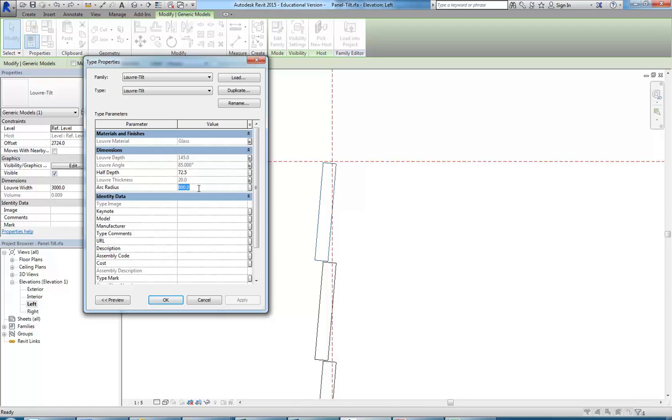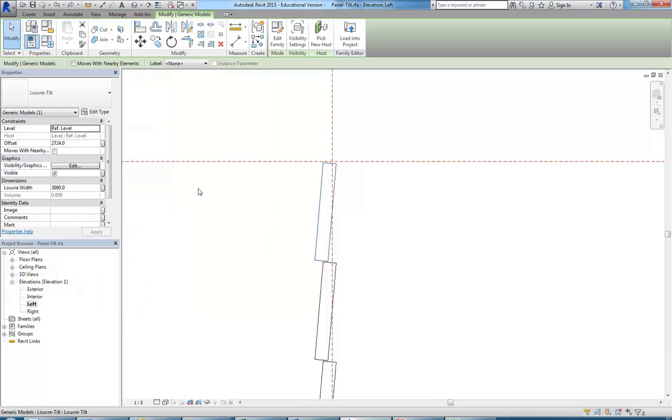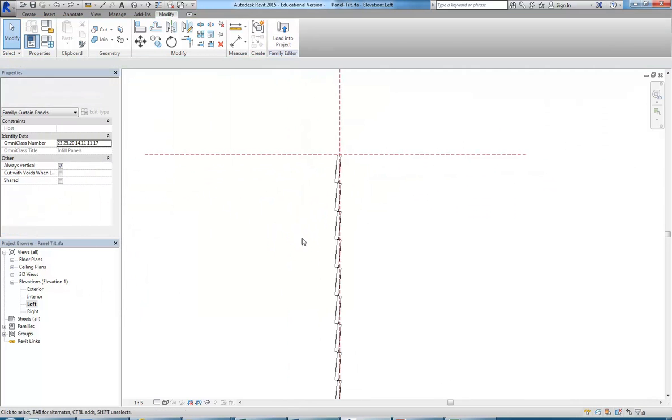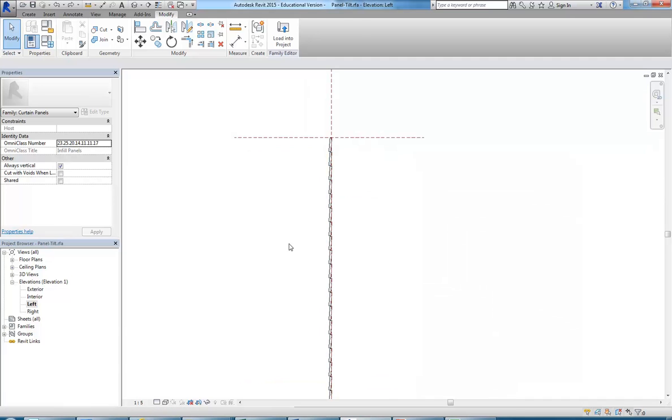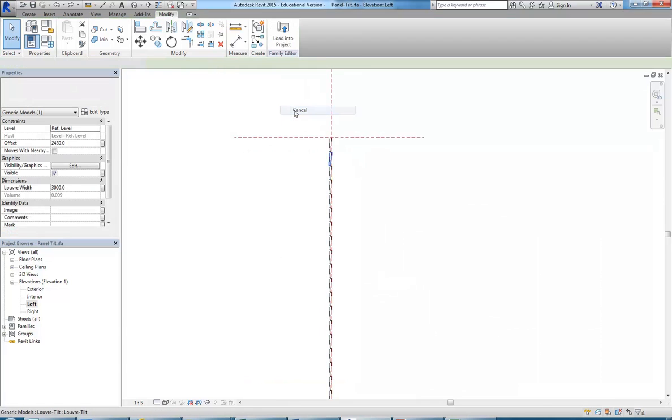And that's the way, if you find that you want complex parameters, and especially when you have repeated objects, try to use families, separate families for each of those. So basically the rule of thumb is anything that's duplicated. So in a desk, for example, you might have 4 legs. Each of those legs should be done with the one family that's then nested into the desk family. So we'll go further with that as you work through your project, but hopefully that'll give you some ideas about how you can work with your own families.